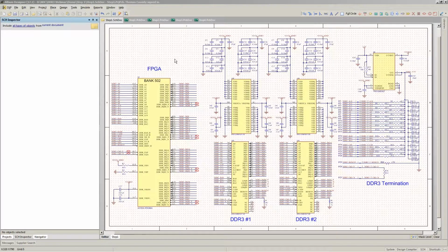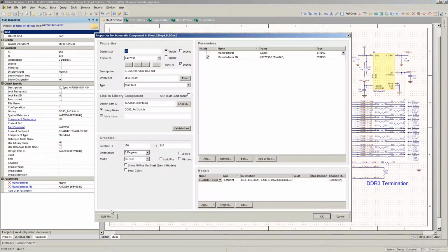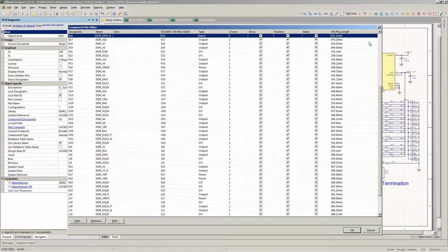So what you need to do is take that into account before you do your delay routing on your circuit board, or you could have perfectly matched traces, but the internal delays within a package can totally throw everything off again. In Altium, basically what they let you do is edit. You can assign a value to each pin. Altium uses distance measurements. They don't use delays. So what you have to do is convert any delays you get from the manufacturer into an equivalent distance of trace, using the basic formulas for the dielectric constant.